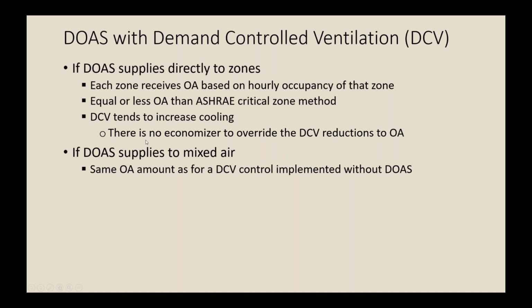So depending on your climate, you may find that demand control ventilation for a DOAS system where there's no economizer override, then there's an energy penalty.